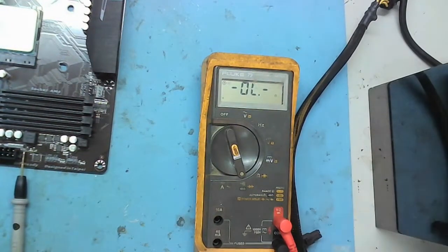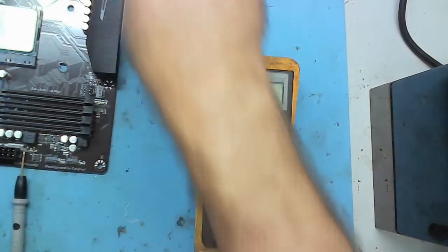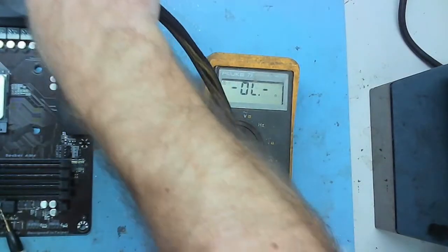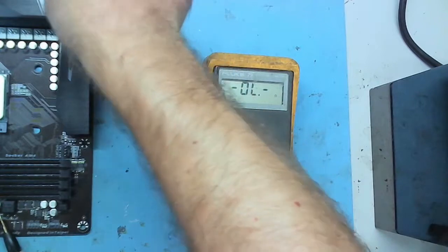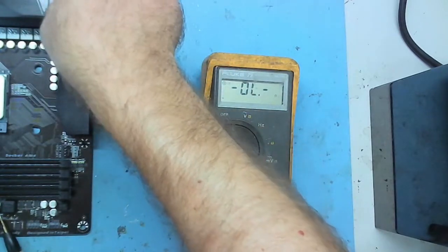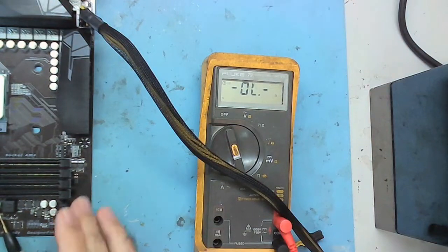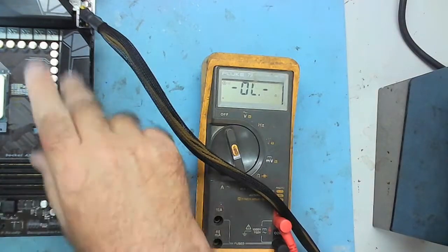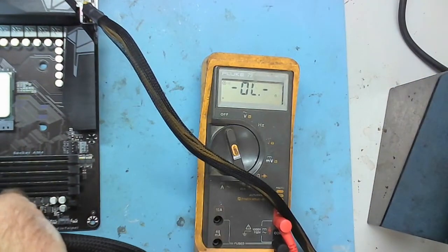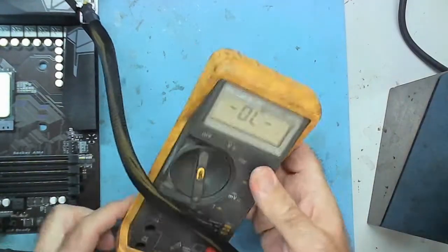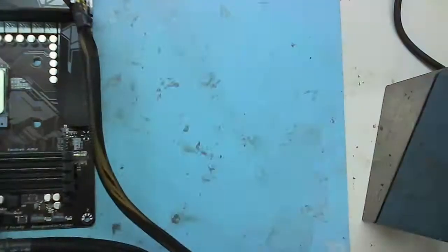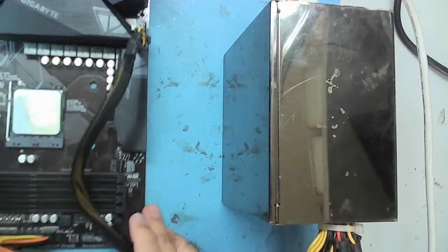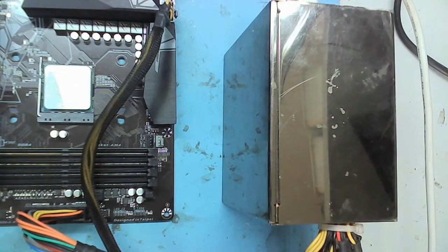Power supply's turned off. Stick this thing in here. 12 volts. In. Okay. What we got? ATX power. There's just an 8-pin on this one, even though it's the same chipset and the same processor type. These think that 8-pin power will do the job, whereas the MSI thought you needed 12 pins, 4 and 8. Is that overkill or was this underkill? I think it was just overkill.